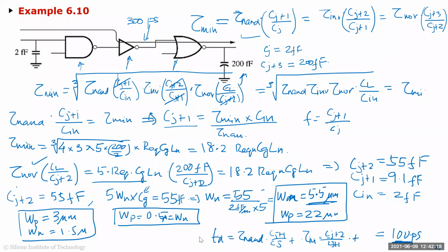I know it could be a lot of info right now, but as I said, just get an overall idea. The overall idea of what we have been trying to do is minimize basically a certain path, right? So you have a series of inverters. In the first case, we took a load and we want to drive it and minimize the delay.